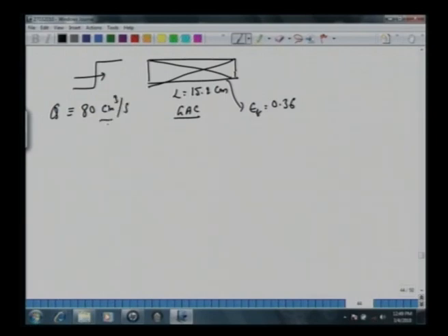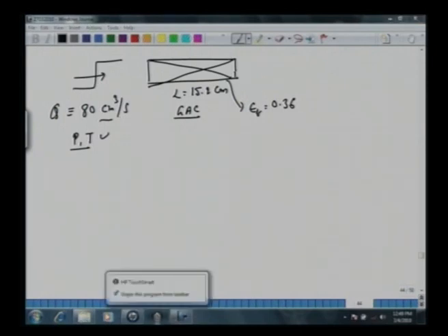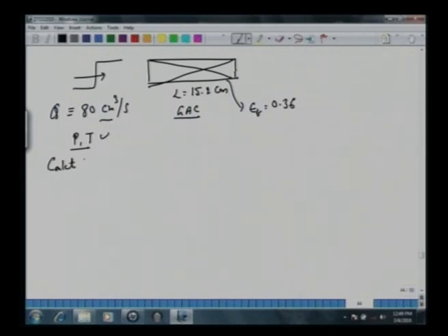Whenever we say gas volume, one has to specify the pressure and temperature. Let's say whatever P and T we have, the flow rate of the gas is 80 cubic centimeter per second. This has the inlet concentration, C inlet. Let's say it contains a certain volatile organic compound, an undesirable compound, at 190 ppm. What is ppm? For a gas it's volume by volume, right? It's 190 times 10 power minus 6 mole fraction. So it's 190 ppm here. Okay, the diameter of this column is 2.3 centimeter.